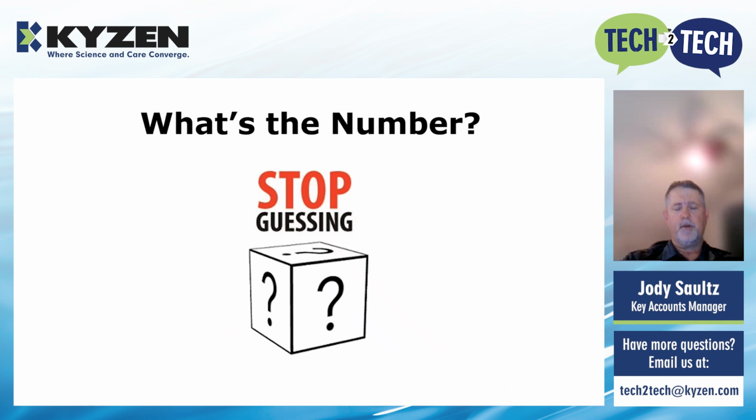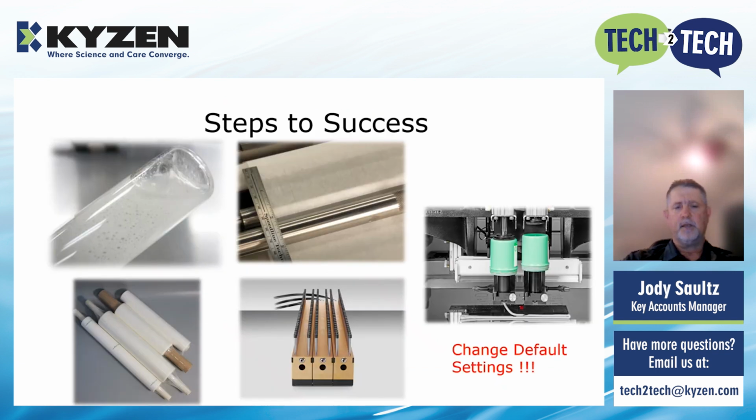So what is the right number? I say stop guessing, do your work. There's steps to success that you can do to optimize your printing process. That includes using the right chemistry that works very well with whatever paste you're using. There's water-based and solvent-based chemistries out there, so it can be covered from both ends.